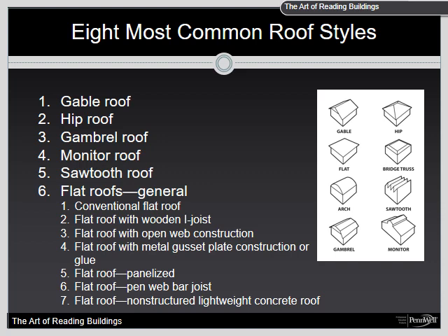The advantages of lighting and ventilation are a benefit for commercial buildings, but can also be used for offices, storage, or extra sleeping areas. A side benefit is that the center section can provide the necessary height for such things as RV storage. Construction can vary, but is typically dependent on the era of construction. Older buildings used conventional construction of 2x6 or larger structural members and were often integrated with pole barn type construction.